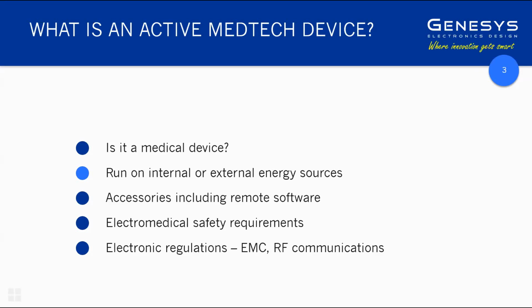Beyond that, there are a whole range of other regulations, such as around EMC, which is electromagnetic compatibility. That's that annoying sound when you're driving along the freeway and suddenly your car radio goes haywire because some electronic or electrical system is bleeding radio waves and interfering with other devices. So you have an obligation that your medical device isn't going to interfere with other devices. And vice versa, if it's a medical device, you want it to be immune to the interference of other devices. So that's another aspect of that.